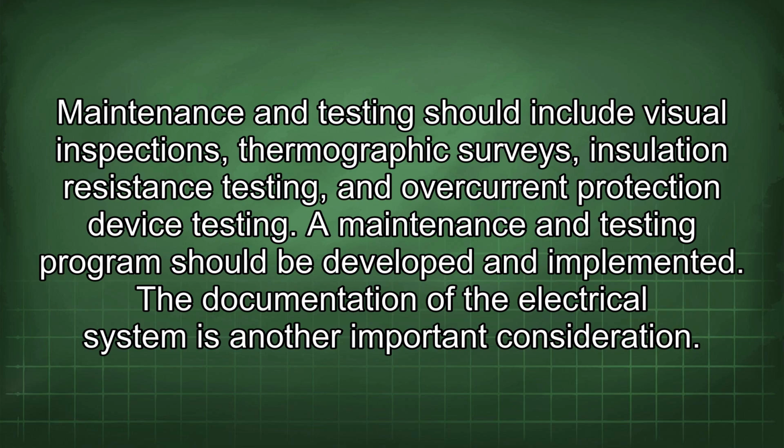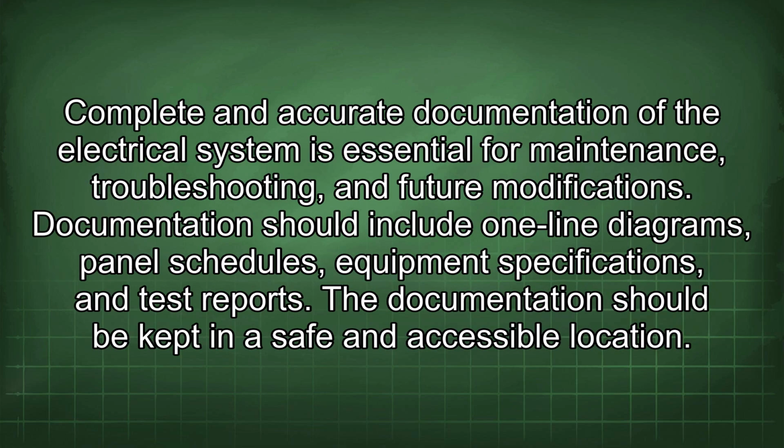The documentation of the electrical system is another important consideration. Complete and accurate documentation of the electrical system is essential for maintenance, troubleshooting, and future modifications. Documentation should include one-line diagrams, panel schedules, equipment specifications, and test reports. The documentation should be kept in a safe and accessible location.